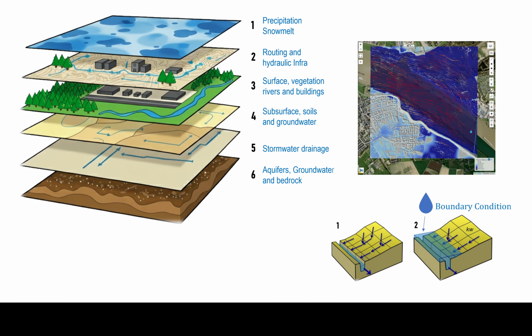Now, that gives us an issue because we are not collecting all of the data for the basin that's upstream, the entire river system upstream of that point. So what we do instead is we provide boundary conditions. These boundary conditions feed water into the model domain at the edge of it, and that helps us deal with incoming water from riverine systems that are large and coming into the simulation domain that the user selected. These boundary conditions can be set by the user, but can also be set automatically. So there's a no-intervention automated setup as well.